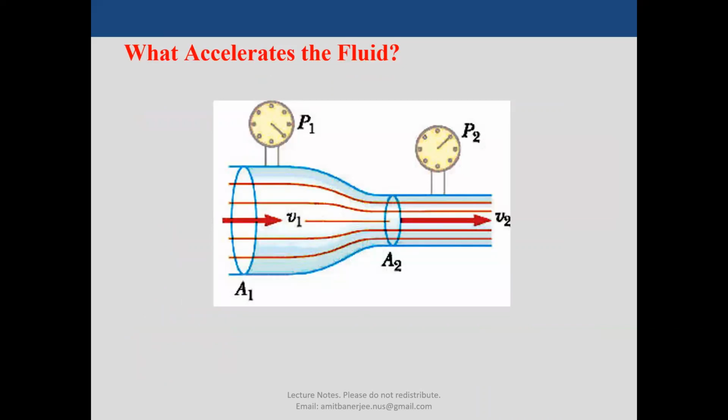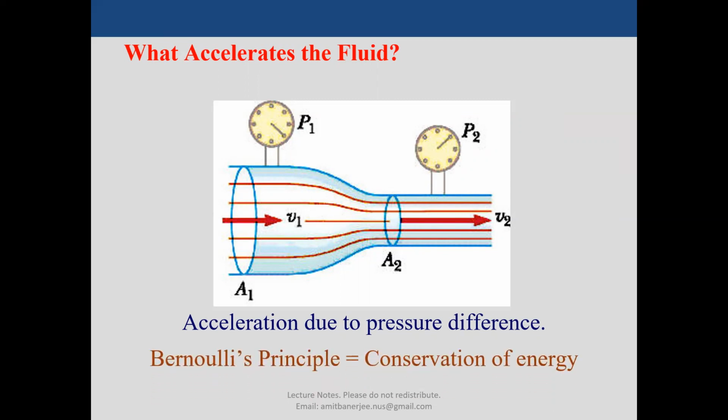Now that is automatically visible from this image, that is what accelerates the fluid. As we discussed, the difference of pressure between these two points, P1 and P2, is largely the cause of the acceleration. And that's Bernoulli's principle. Bernoulli's principle comes from the conservation of energy.